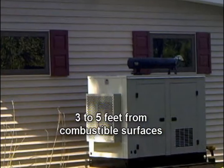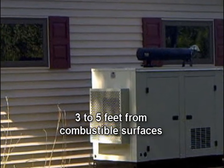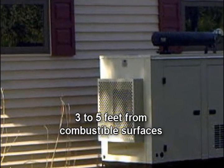If you're next to a cedar shake or vinyl siding, 3 to 5 feet is really where you need to be away. 5 feet is perfect. 3 feet, you're pushing the envelope. Can it work for you? Yes. So you need to be really, really careful of that. We have seen vinyl siding melt from the generator set being 6 inches away from the vinyl siding. Not a safe issue.